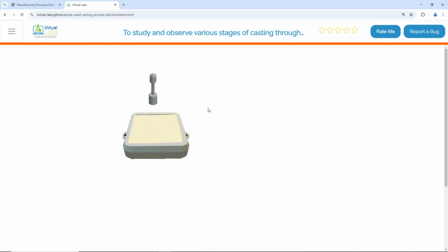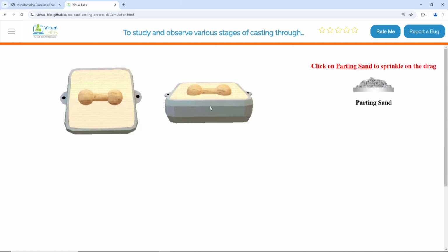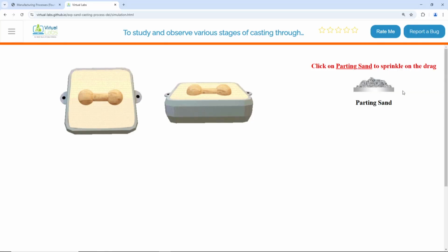It is rammed, and this ramming is generally done manually for the sand casting process. There are automated systems to also do ramming, but the strength of the ramming has to be controlled, as it has to be dispersed later. Core strength is more than the pattern sand strength. Core making I also do as an experiment here. So here it is rammed. So this is the drag. The upper part, the cope, also is to be made, but the sand has a cohesiveness property.